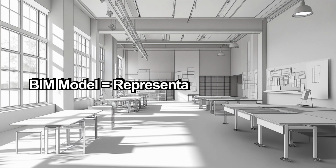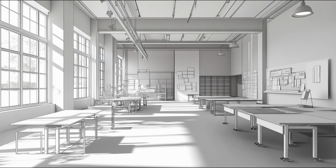One common mistake young professionals make when they're starting out is over-modeling. It's easy to get carried away, thinking that the BIM model needs to be a hyper-detailed, video game level representation of the building. That's not the case. It's important to remember that a BIM model is a representation of the building, not a perfect replica. The goal is to balance 3D modeling with 2D detailing. The model should contain enough detail to effectively communicate design intent and coordinate with other disciplines, but not so much that it becomes unwieldy or distracts from the core objectives. Over-modeling can lead to unnecessary complexity and even slow down the project.